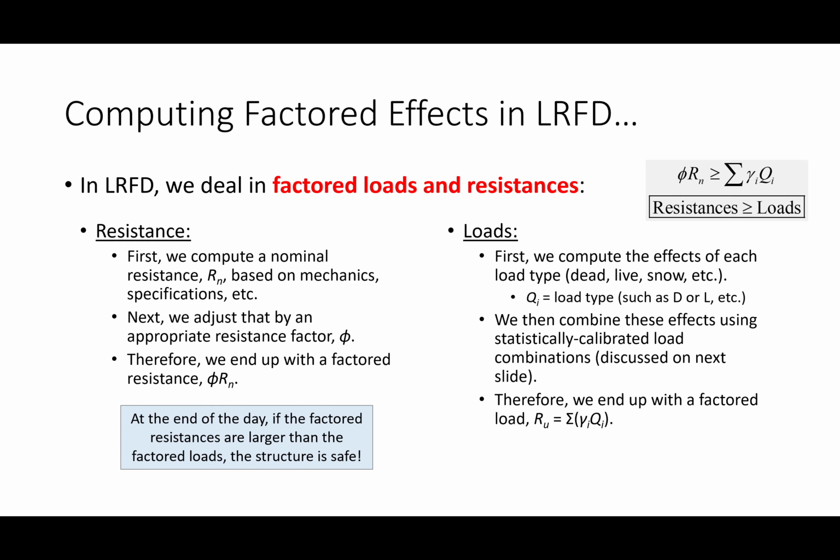And so that resistance factor changes dependent upon the limit state that we're looking at. A good example of what I mean by that is, when we look at yielding limit states, a common resistance factor for yielding is 0.9, but a resistance factor for fracture is 0.75. So why is the resistance factor lower for fracture? Well, if a member yields, what happens from a mechanics perspective? Remember in materials, if you have a piece of metal and it yields, all that means is that it gets longer. That is bad if it's causing undue stresses in other elements, but it's certainly not as bad as fracture.